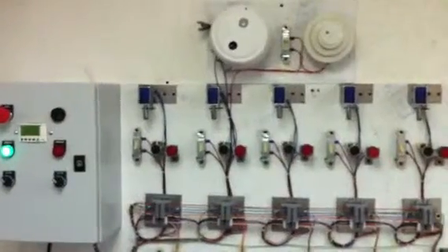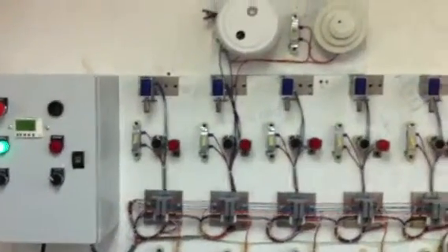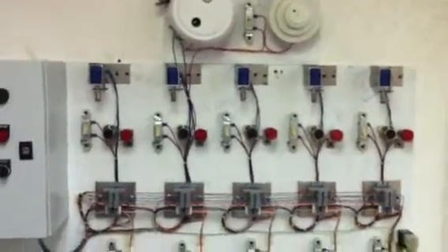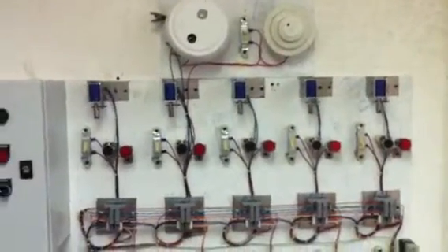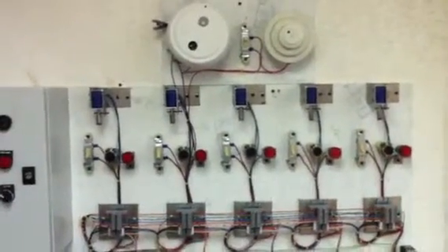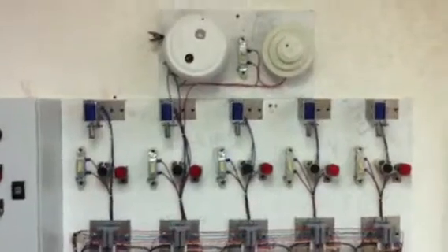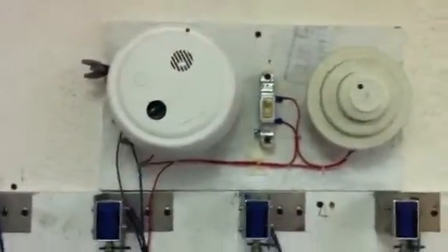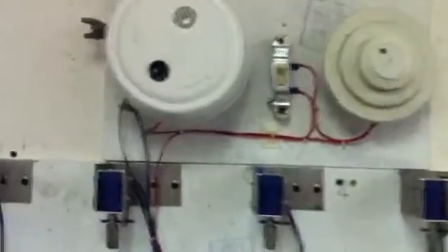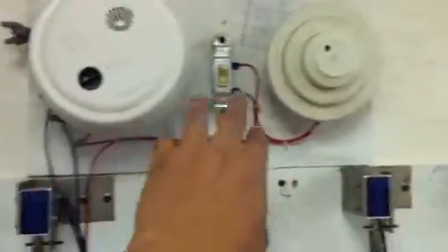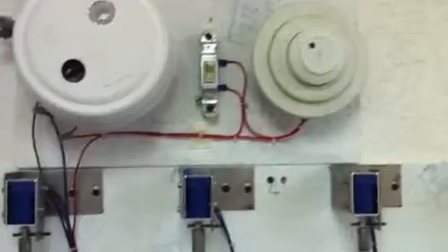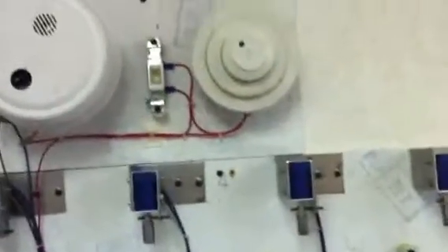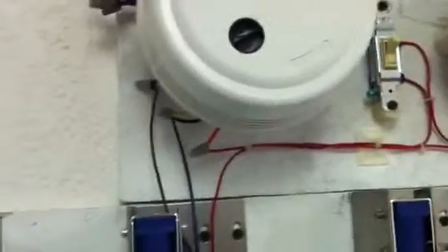In this video, we will show the capabilities of monitoring of the system through the smoke and fire sensors. These two devices up here are usually mounted in the trash room, and they send signals when there's a smoke condition in the room or an increase in the heat given by the heat detector. Now, these smoke detectors and heat detectors are always normally closed systems.